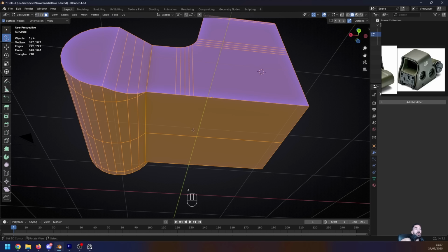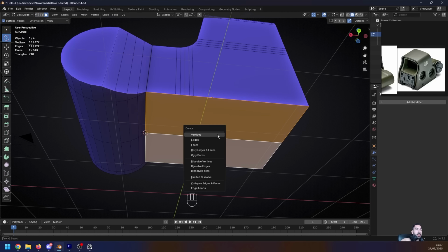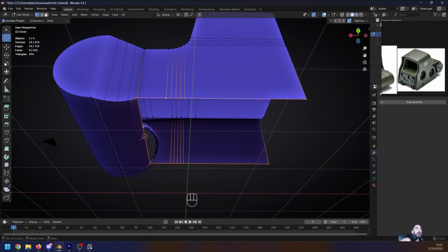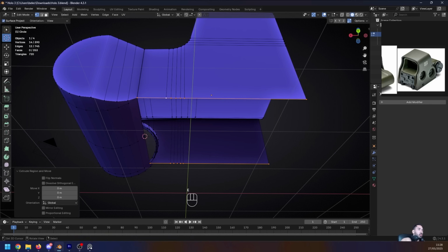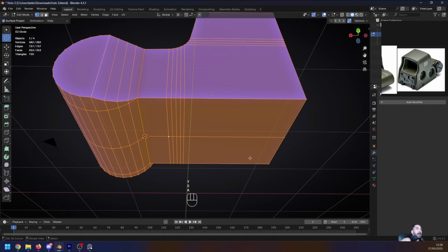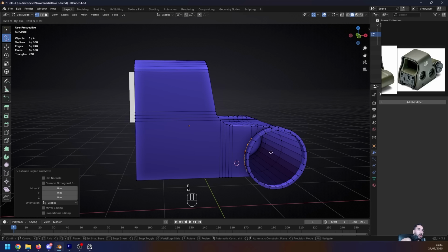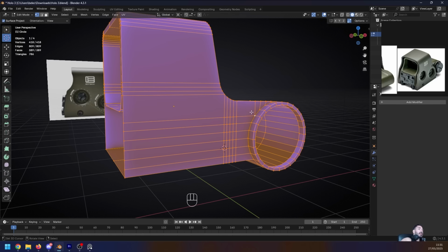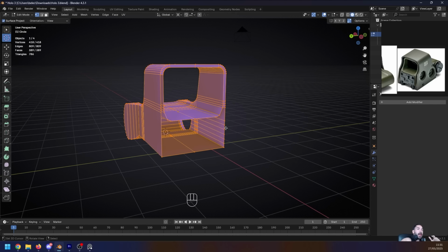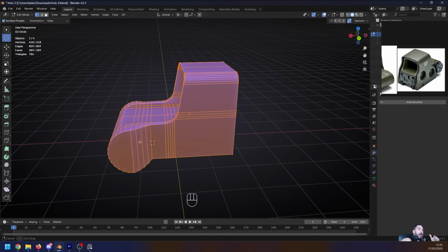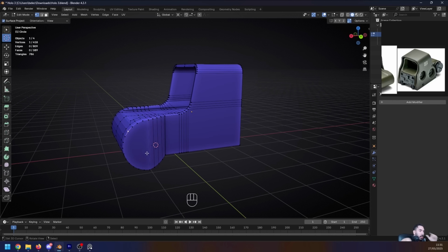And now down here at the bottom, I'm just going to place my cursor in the middle, delete these two faces, select this outline, delete the vertex on the inside, extrude, right click, scale to 0 on the y-axis. I'm gonna select these other edges down here. I'm gonna extrude them backwards. Now I got some more edges down here, so this is going to allow me to connect this side to the other side, and then I'm gonna be able to get rid of this end going over here as well.